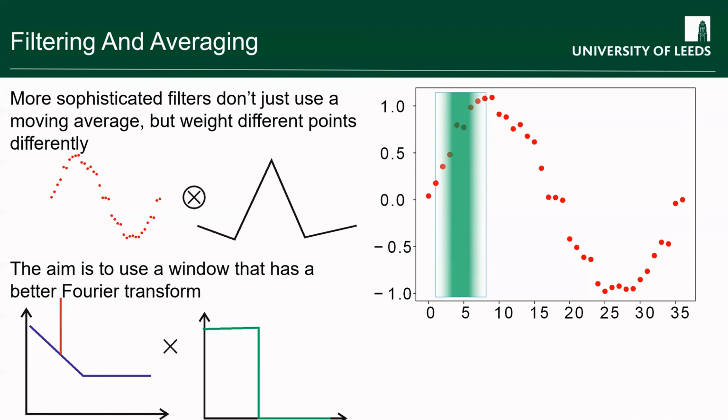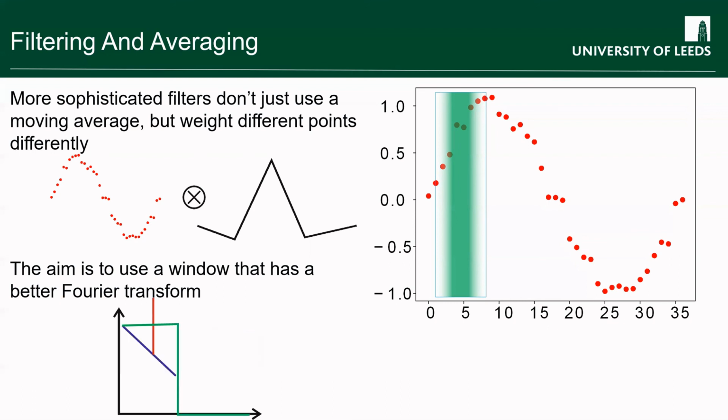Now what this is telling us is that we're going to have the same noise spectrum with the signal that we had previously, but now we multiply it by something which is basically 1 for low values of frequency, and then immediately goes down to 0 and cuts off all the higher frequencies. And so the signal you get doesn't have that distortion of the high frequencies coming back in. It's a much better behaved signal.